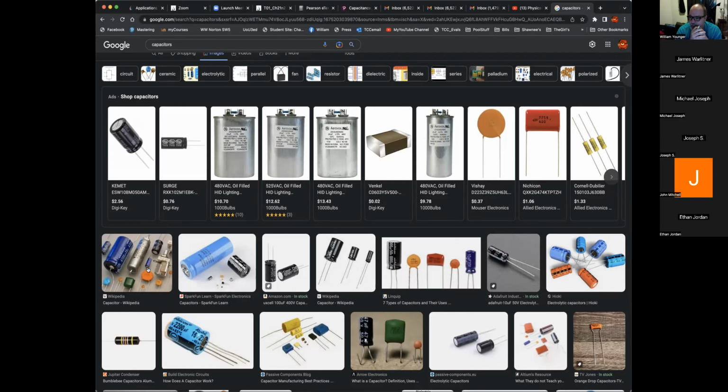one of them to a ground wire, basically a wire that you can stick into that little half moon looking mouth of a receptacle. That's actually ground. So I stuck it to that, and then I touched the other one to it too. That way I knew at least that the capacitor was discharged. And then I cut the capacitor loose and resoldered my capacitor right in place.